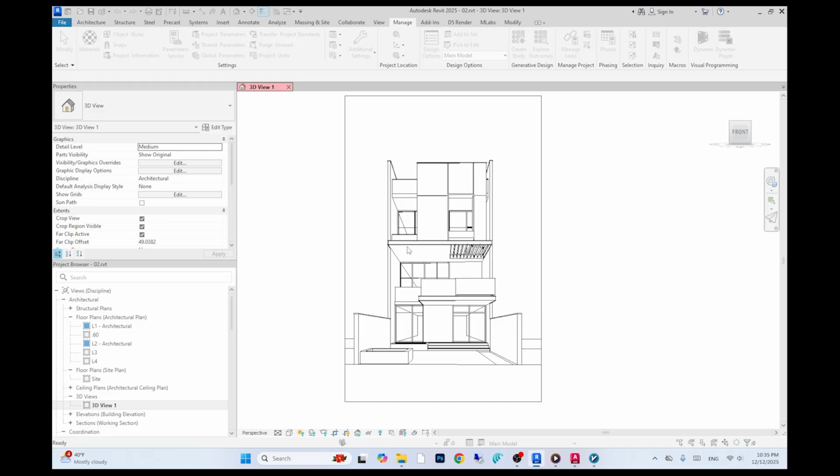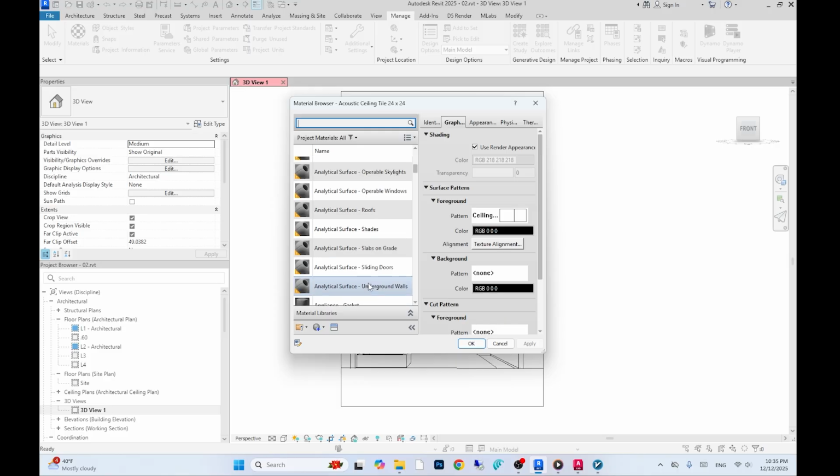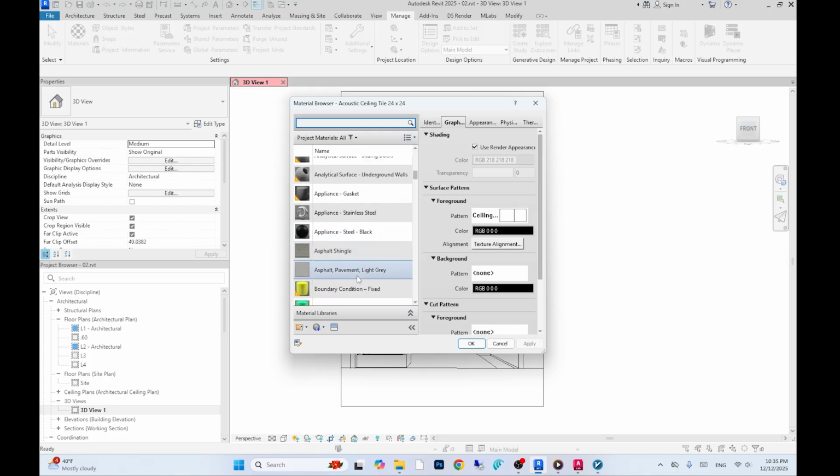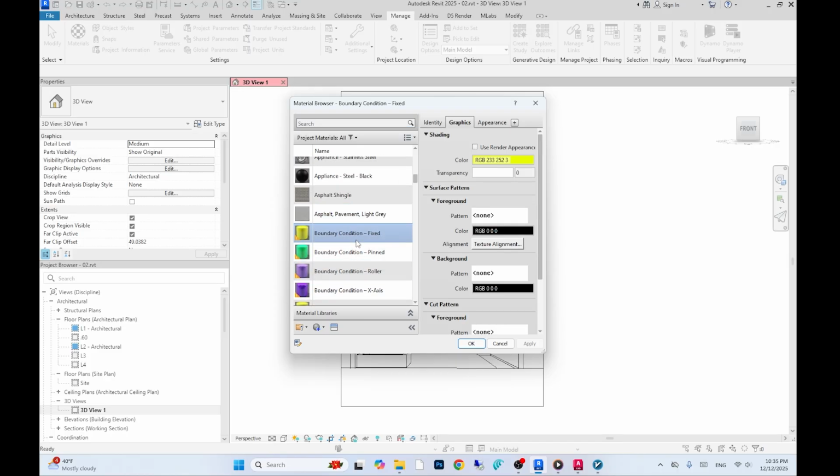Revit materials do not need to be realistic or final. They mainly work as a label to define how elements are separated during rendering. If materials are not assigned correctly in Revit, controlling and adjusting them later in D5 becomes difficult. But for this, all we need to do is understand how many materials we need in the materials panel.